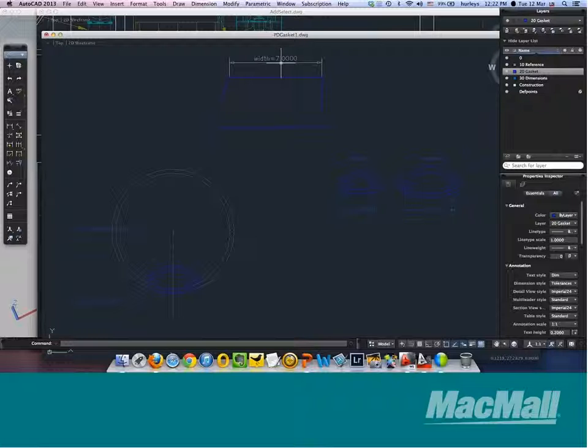And we can say it's 7. You see how it controlled that top there? So that dimension there, actually, if I come in and say now 10, you see it changes that. And I could have had those two sides also constrained so that when I did that, the whole box changed. So it's pretty nice to have those geometrical or dimensional constraints.